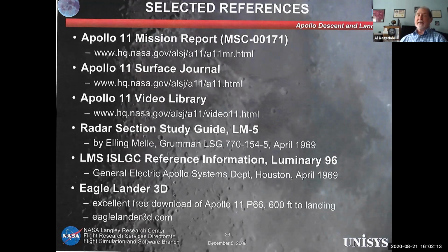And there's orbital mechanics too. If you're some distance away from a spacecraft and start firing forward instead of flying towards it, you go towards it and then you climb because of orbital mechanics effects. If you're going faster than the command module, then you're going to climb. And we had to convince some of them that was real.